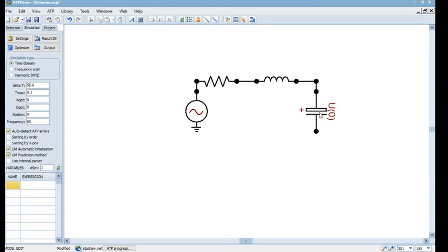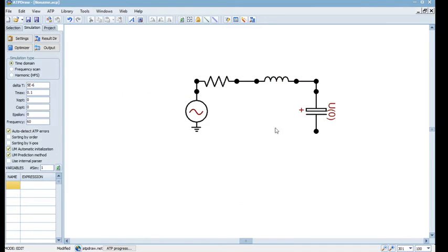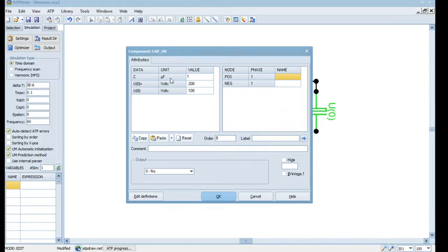So same thing goes here. If you set X opt as 50 or 100 hertz, then pertaining to that frequency, you need to specify what is the ohm or reactance value. Now we have set everything to DC, let's say 0. So you need to specify the exact value of that. If you come to capacitor, you need to specify what is the capacitance value. So I guess it should be 10 microfarad.